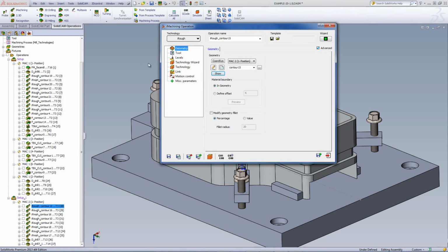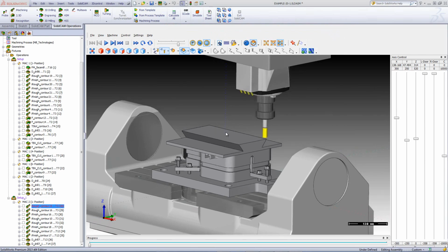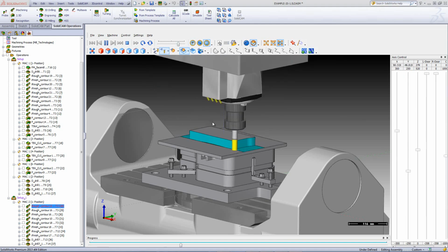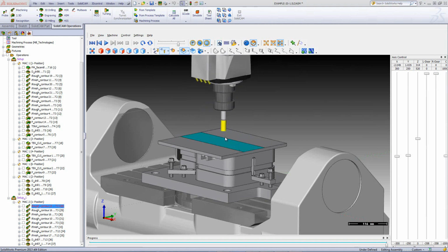Now, the material that was left on top, if we take a look at our simulation, was actually this area over here. So my geometry was actually made just to go around this area, clearing up this excess material over here. Running the simulation, you'll see that the iMachining works just on that area over there, cleaning it up very, very quickly.